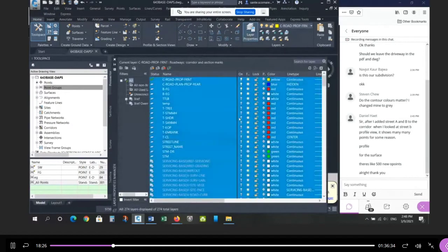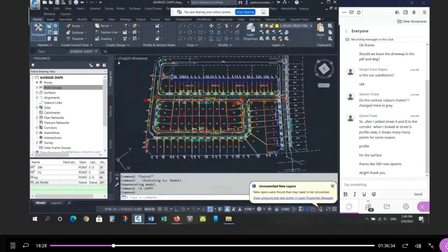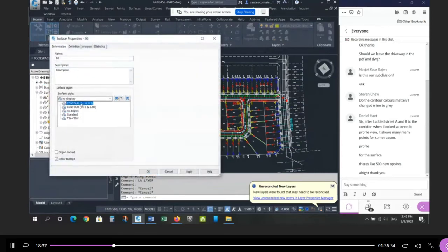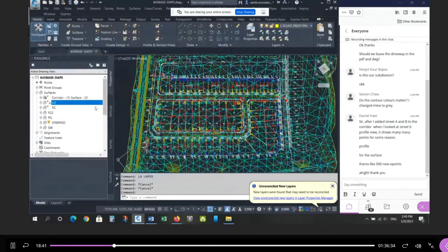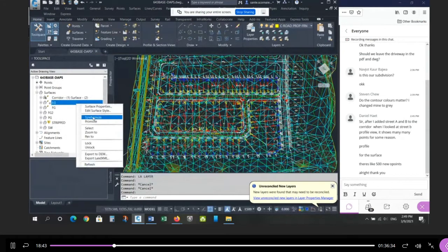Once your design is ready to go, I would freeze out the drainage areas and just have all of this showing, including the existing ground. I want to see the existing ground contours. So there's a spec for this. These are different. Again, these are not the specs I want. I wanted a 1/4 meter. Whoops, and I don't want the tin lines.